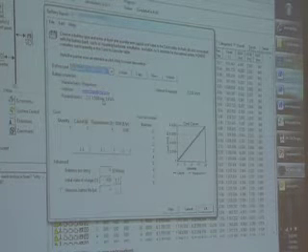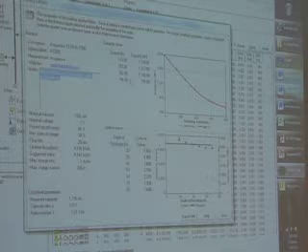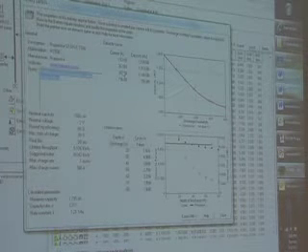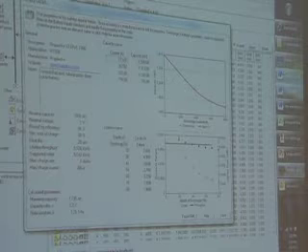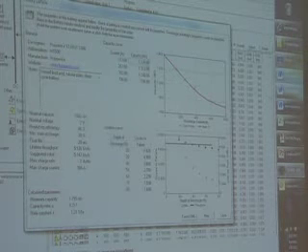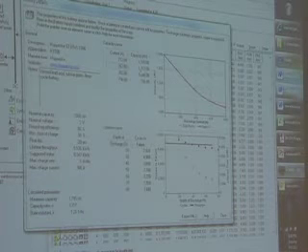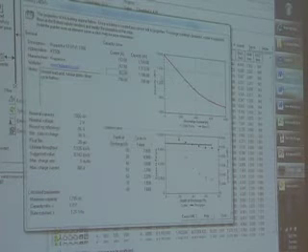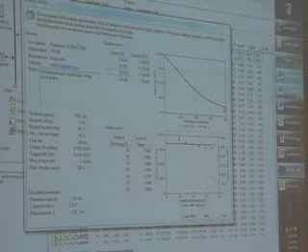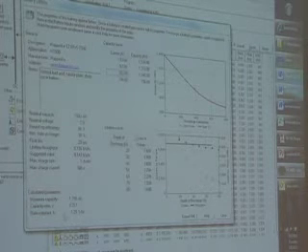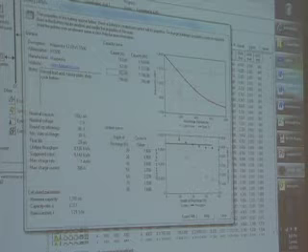So let me take a conventional battery here and give you an example of this. Here's where we filled out the capacity curve for the battery from so many amp hours of capacity. If you're discharging at this rate, if you're discharging at a higher rate, you get less capacity. Those are the little diamonds. And then we do a best fit of the 3 kinetic battery parameters to fit the data.